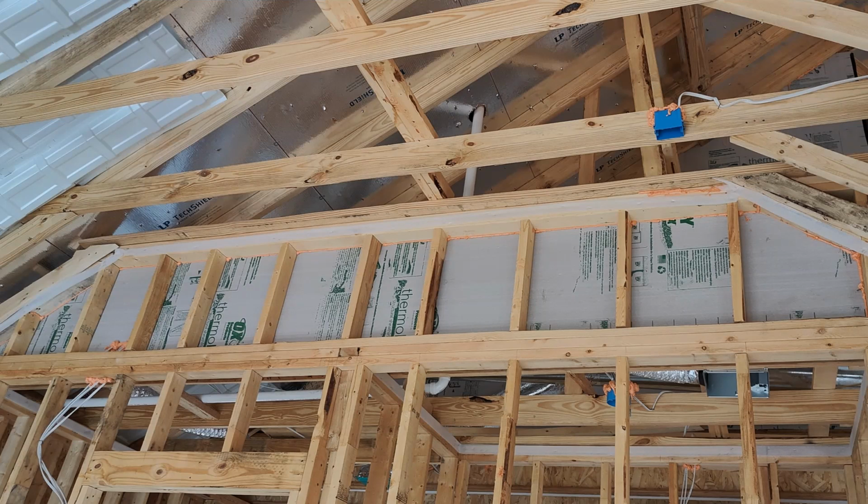So if you're on the heated side in winter and you're up in a northern climate, you're heating the interior, that heat is easily transferred through that insulation and then radiates into the colder attic space. Putting an air barrier there will stop or slow that down. Same for southern areas, where we're trying to keep hot attic air out of the insulation from getting to the colder surface inside the house.